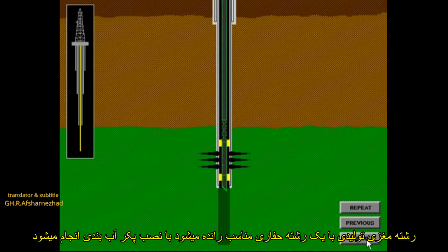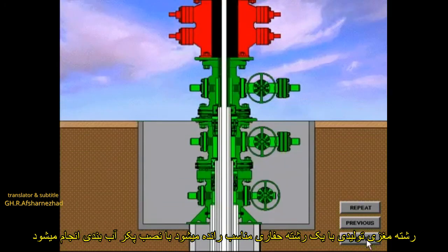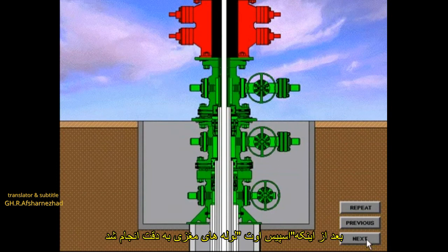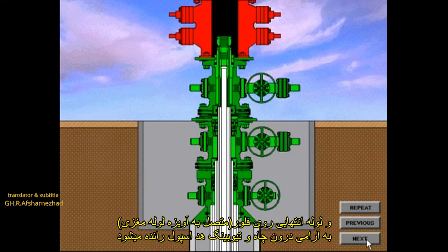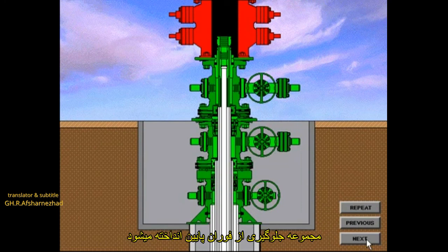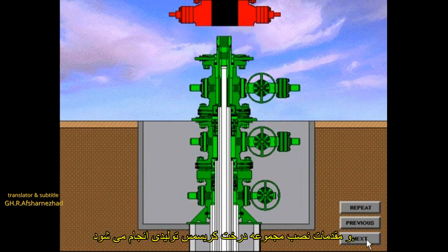The production tubing is run with a bottom hole assembly to seal inside the packer. After the tubing is spaced out and proper weight set on the packer, the tubing hanger is installed at the tubing on the rig floor, then lowered into the bowl of the tubing spool. The BOP system is nippled down and preparations are made to install the production Christmas tree.